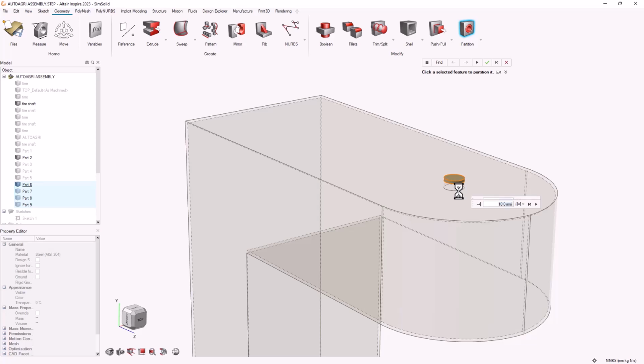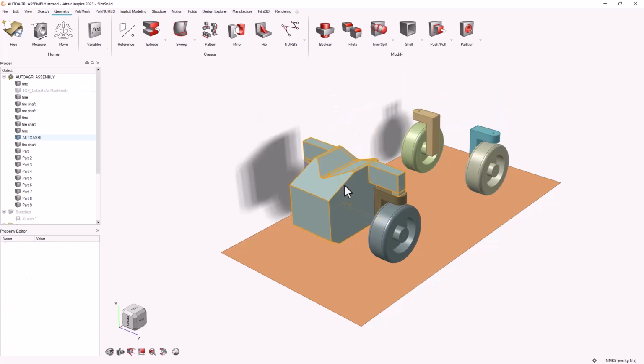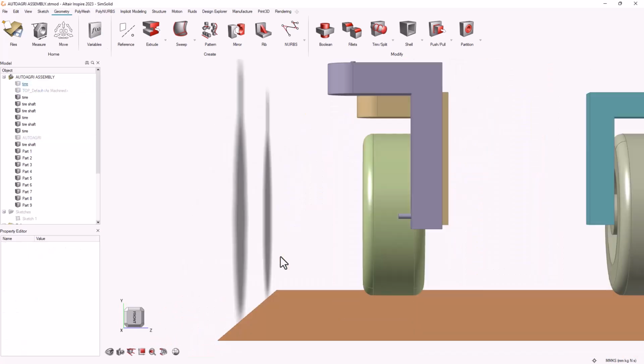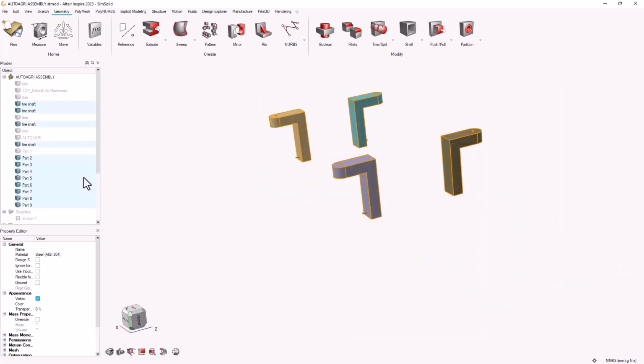Since all four joints are linked together, I used the partition tool, located under the geometry options, to section some parts on the joints. To keep my workflow efficient, I selected all four joints and broke the instance that links the components together. These steps make it easier to track each part independently during optimization and also reduce the computational strain on my system.